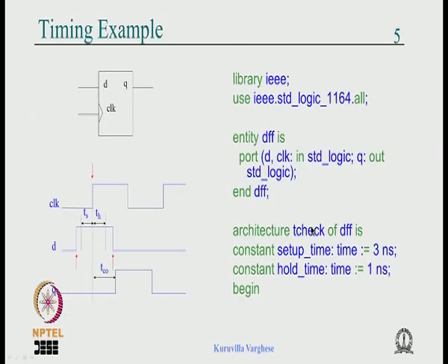We also looked at how to write VHDL code not only to synthesize, but to verify some timing condition on its input. It's quite useful, because sometimes you have some timing violation happening in the simulation, which you suppose is random and you want to catch it, and you can do it this way.